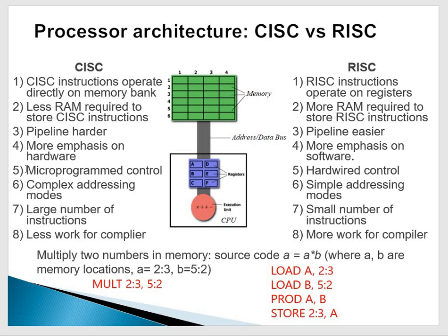As we have already discussed, to perform any operation by the CPU from or to the external memory or I/O, some control signals will always be sent to the memory or I/O. Microprogrammed control is a type of control unit or architecture in which the control signals are generated by a set of instructions, by writing small programs, the microprograms.